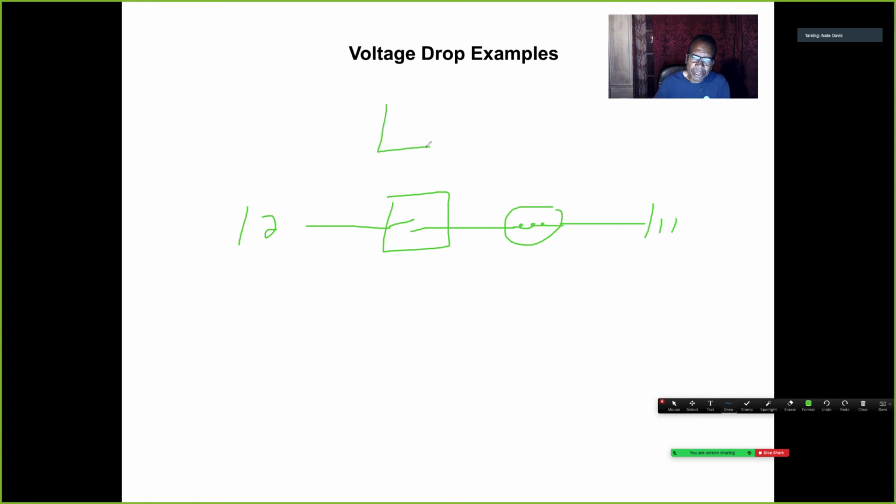Here's the voltmeter. Here's the red lead. And it's ground. And what it's saying is the red lead goes to the most positive side of the circuit. The ground lead, I'll make the ground blue, goes to the least positive side of the circuit. All right, that's what it's saying.